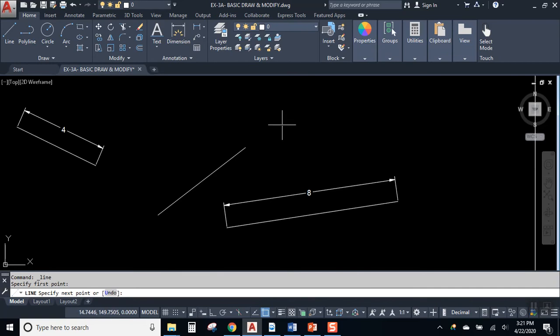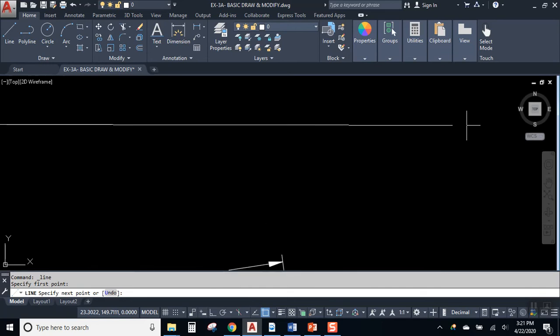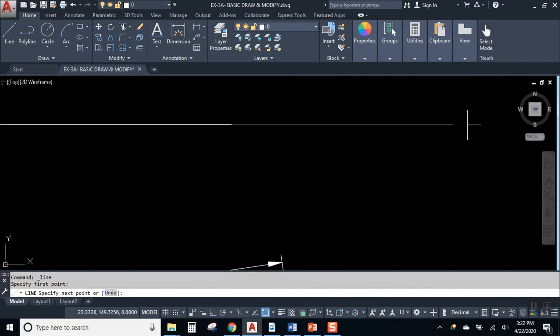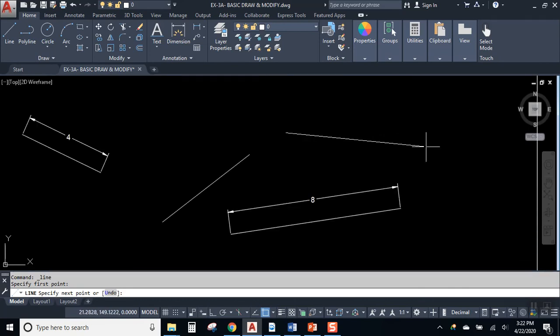And the fact is, if you tried very carefully to go in there and get that line straight using the cursor and using your eye, you're going to fail. Why is that? Well, look, it looks good, sort of, right? Looks mostly good. But then I zoom in, and it's a little bit off. And as I try to straighten it out and I zoom in more, it'll still be a little bit off. So the deal is you're never going to eyeball the line straight in AutoCAD. Eyeballing, bad. Haven't we already figured that out?